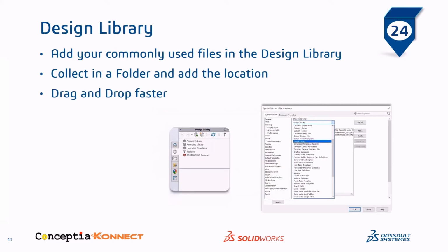Number 24. Design library. Add your commonly used files in the design library available in the task pane. Collect the files in a folder in Windows Explorer and add the location in SOLIDWORKS to use. Use them with a drag and drop into the SOLIDWORKS screen.